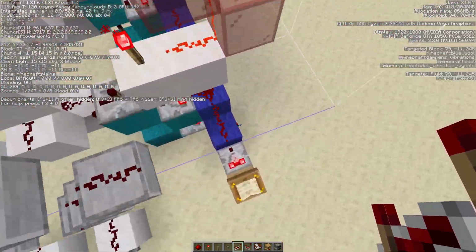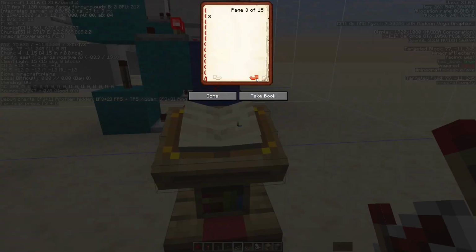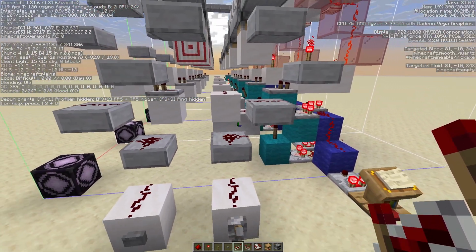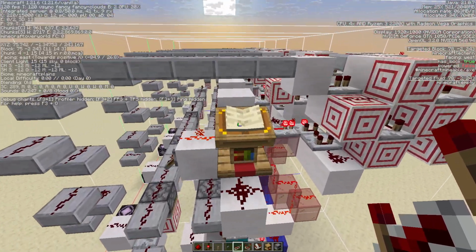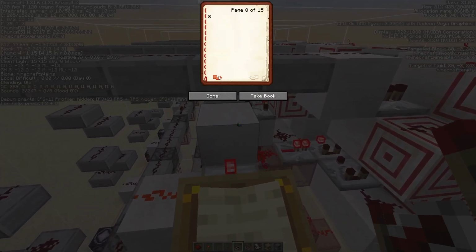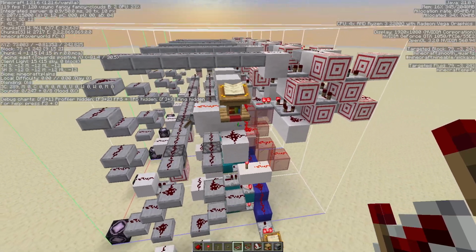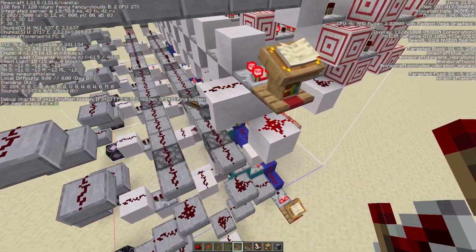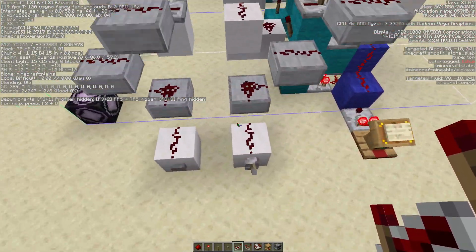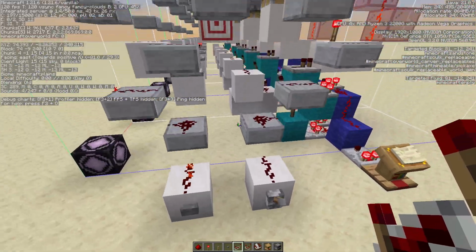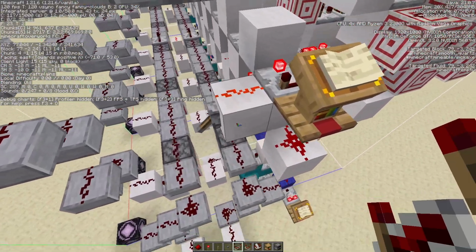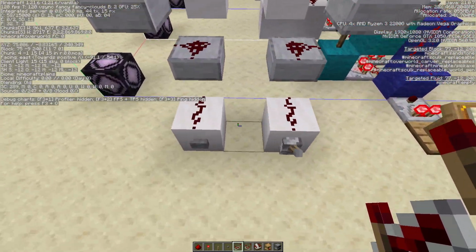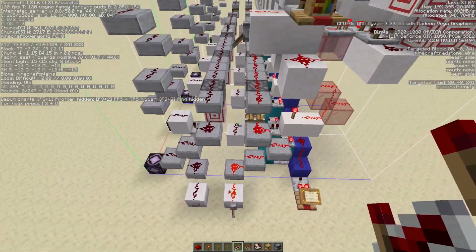Let's do another test. Do I have a number 5? I think so. I do have a number 5. Number 5 will be boom, boom, boom, 7. So 5 is 7. The data bus needs to be on, so I get a 7 on the data bus. I flash number 5. I turn the data bus off, sorry. And then I read out the 5 and haven't done anything.